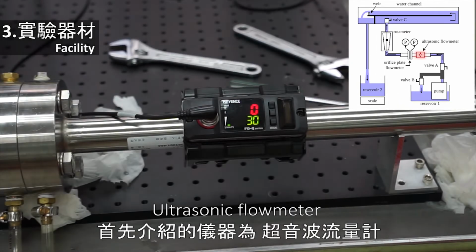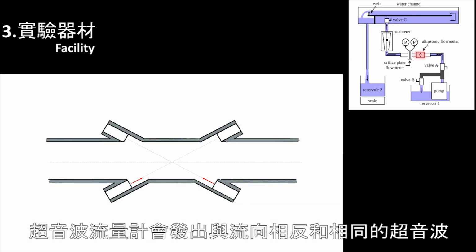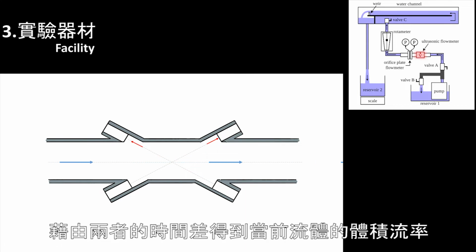Now let me introduce the working principle of these flow meters. The first subject is the ultrasonic flow meter, and we're looking at its digital meter. An ultrasonic flow meter measures the difference between the transit time of ultrasonic waves that are propagating with and against the flow direction. And the time difference here indicates the volume flow rate.